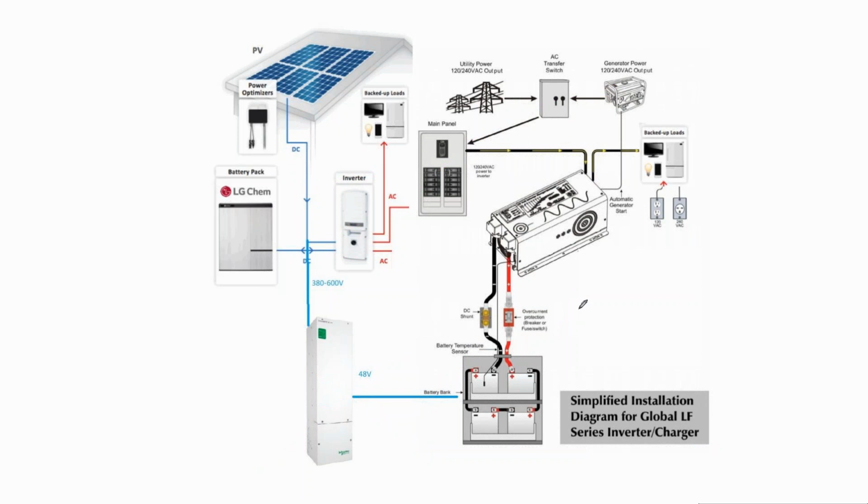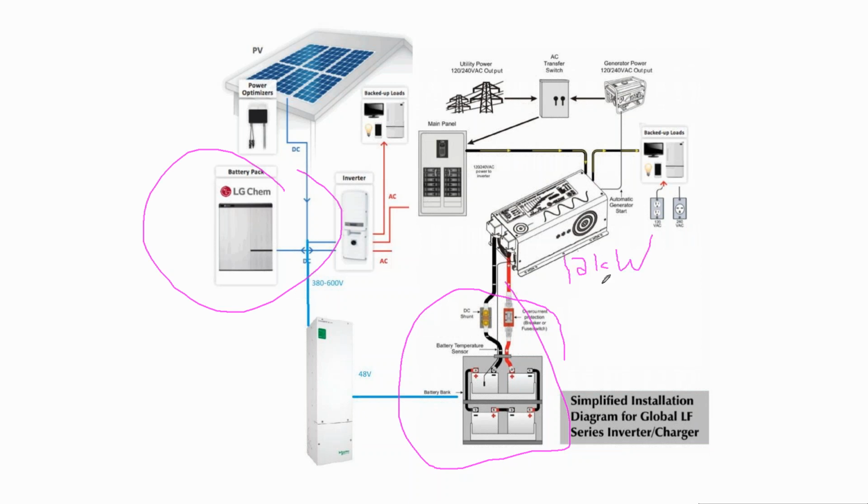Now, another concept is, okay, lead acid is cheap, but lithium ion is better for, say, a tankless water heater, for something that's more dynamic, a burst mode, or responsive. Now, this 12 kilowatt inverter has a burst mode rating of 36 kilowatts for about 30 seconds. So it could still do surge loads, compressor loads, motor loads, things like that.